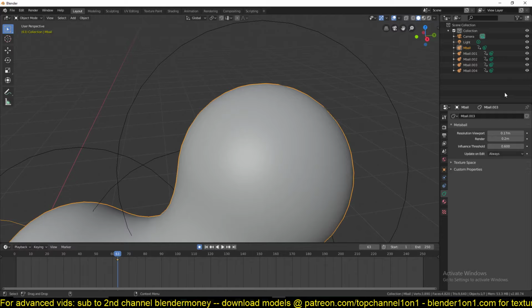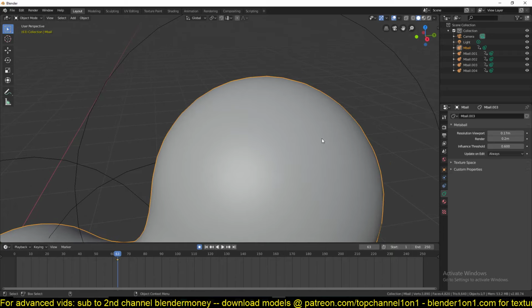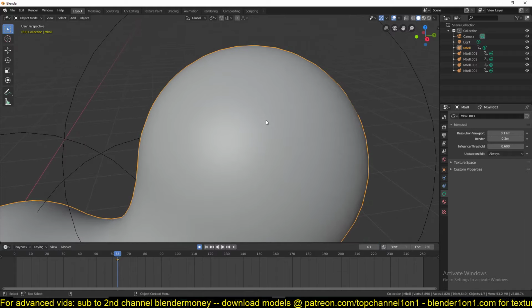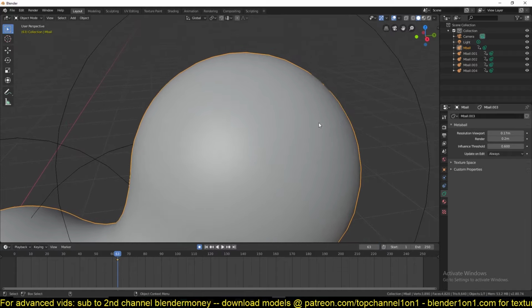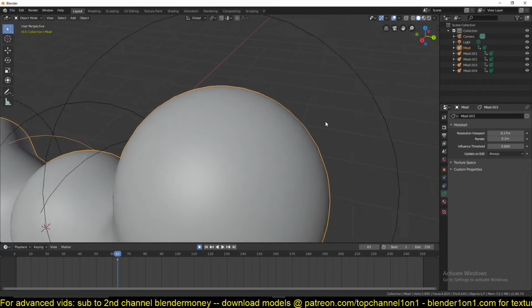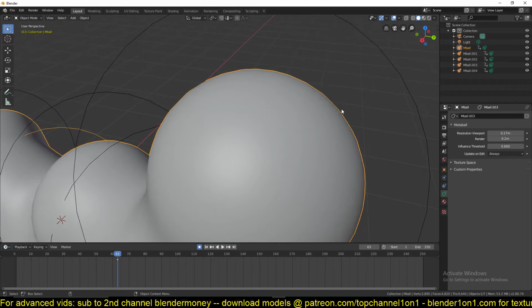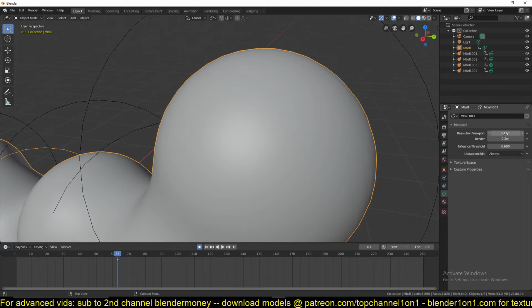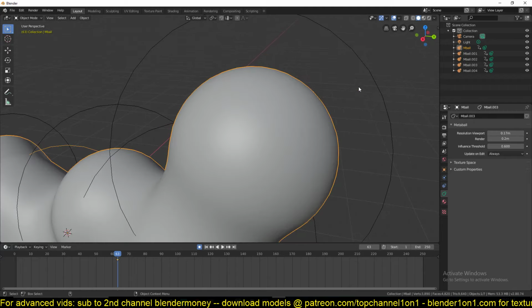We're going to use a lot of them, so make sure you don't set too high a number. It won't make a big difference when you are rendering the particles out, but it will increase your render time, and your PC will also start slowing down if you use too high a number and you have a lot of particles in your scene.